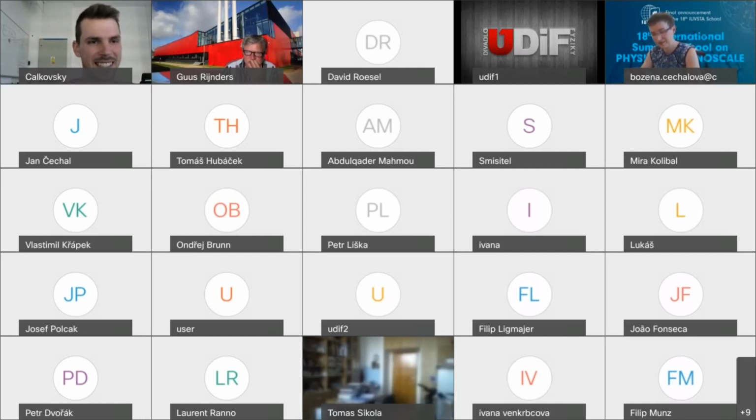Yes, that's a very interesting question. So yes, there are more individual pistons there. That has to do with the wavefront correction you need. Typically, for this application, the piston sizes laterally are in the range of 10 millimeters or so, maybe 20. So if you then would have a 300 millimeter wafer, well, you could almost count the individual pistons. That's enough to do the wavefront correction there. But you can make them smaller. It gets more difficult because you need to control them on an individual basis, right? So you need also to have control lines connecting to these electrodes there. But in principle, I think you can do that. And then I think there was, oh yeah, tilt. Yes, that's a very interesting one.